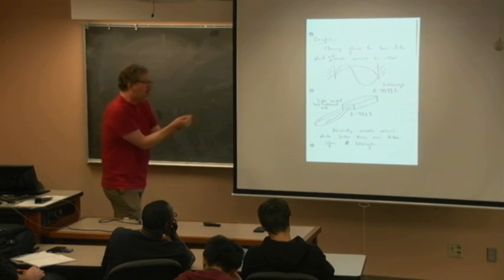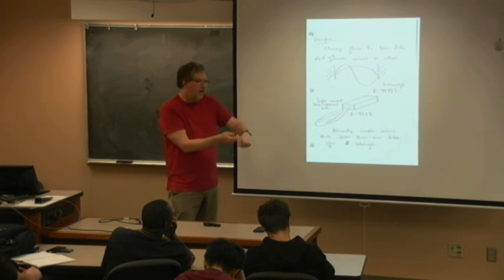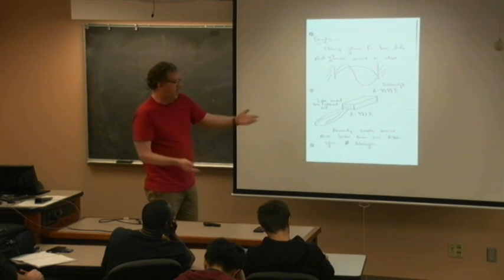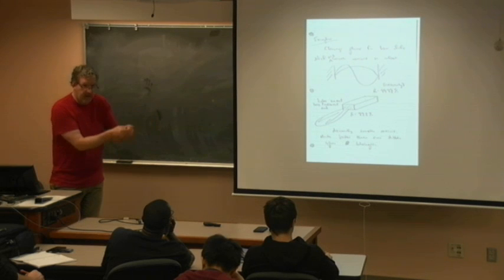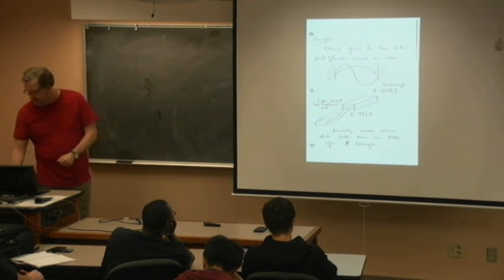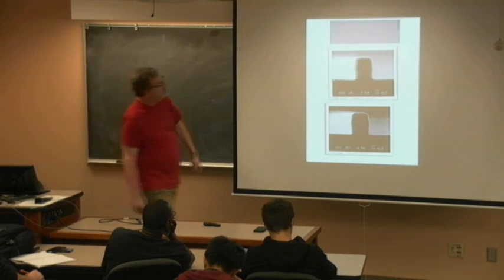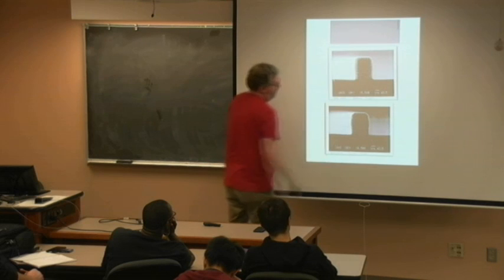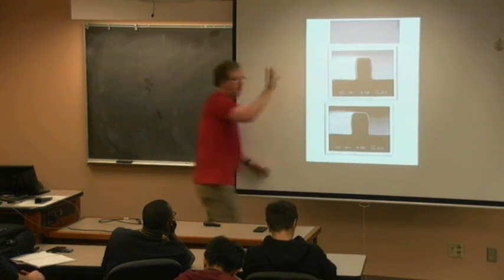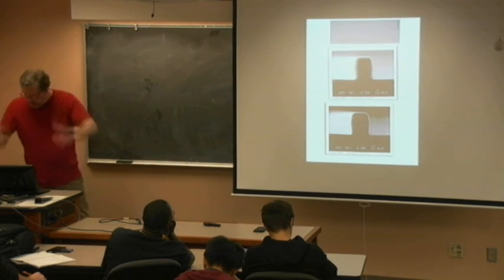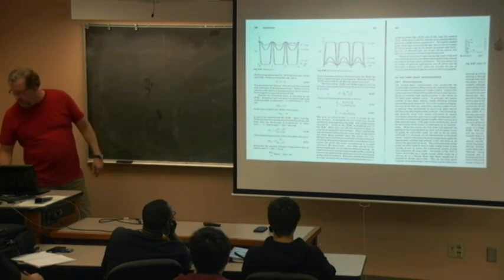And so if I cleave along the facets, I get a nice cleaved edge. If I cleave at the wrong angle, I'm going to get a ratty edge that is going to be a dead laser. So you get fired from De Beers if you don't cleave along the right crystallographic planes. You get fired pretty quickly. So here's some of my old cleaving, some waveguides. I was just trying to throw that in for some eye candy. And then if you remember, so this is not testable. I'm deviating. Let me keep on task here for the test. Yeah, here's the Fabry-Perot.